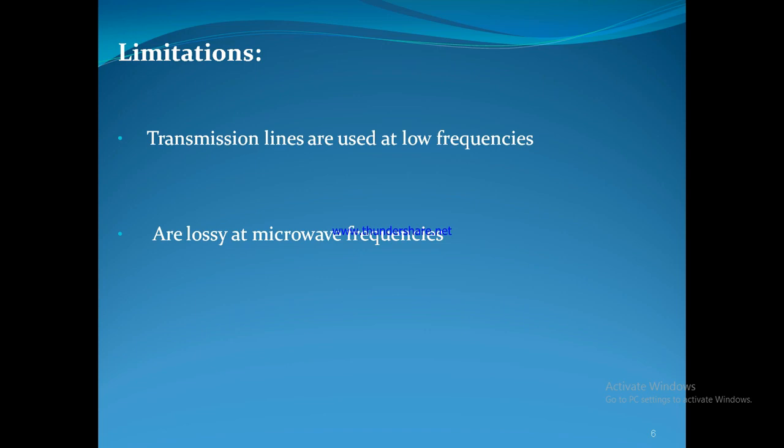The antenna is usually some distance away from the transmitter, or the transmitter is located inside a radio room and its associated antenna is mounted on a mast. A transmission line is used to connect the transmitter and the antenna. So here the purpose of the transmission line is to transfer the energy output of the transmitter to the antenna with the least possible power losses.